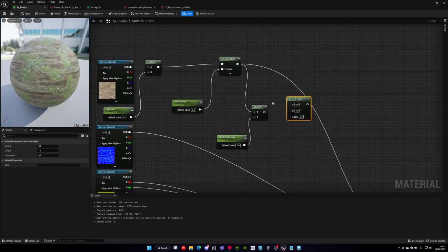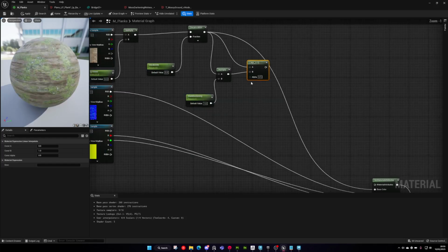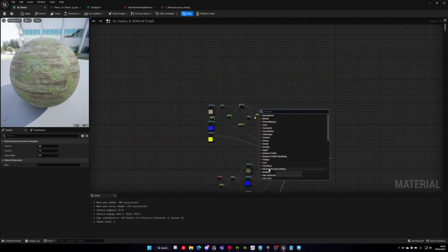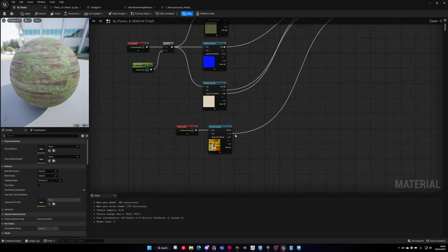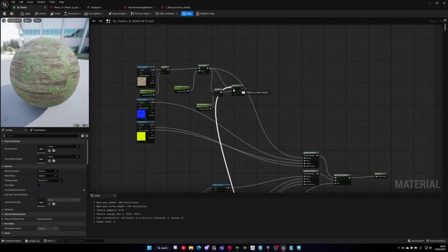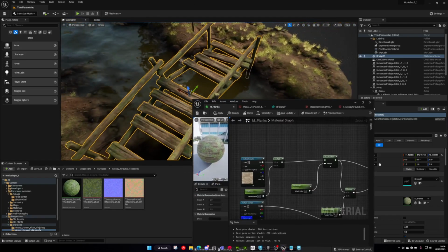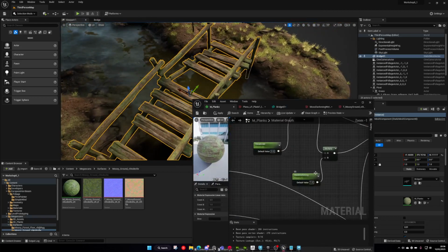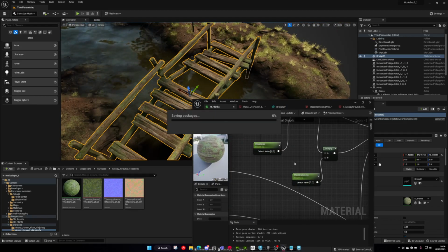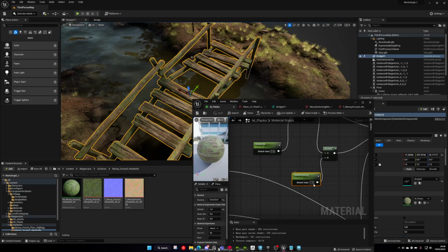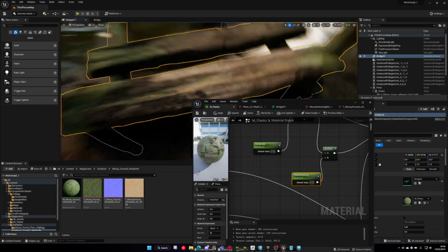And we can just blend between the untouched texture and the darkened texture based on the green channel, which was our second mask. So we've set this to 1 to begin with, so we're multiplying it by 1, so nothing is going to happen. If I just set this to 0, it should be quite obvious. You get that darkening.